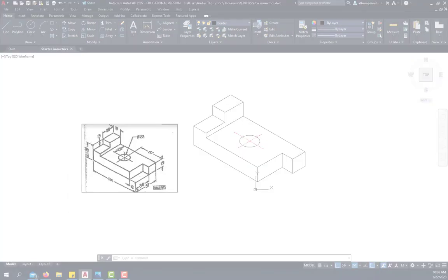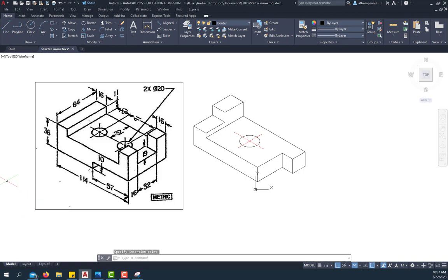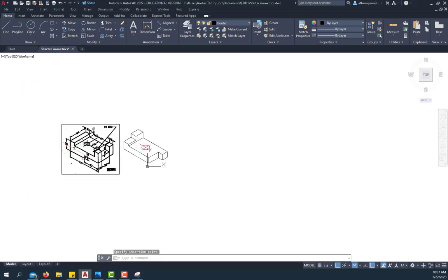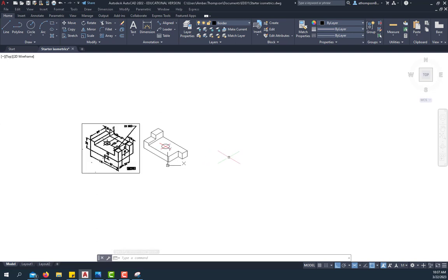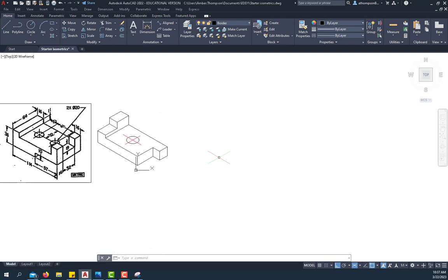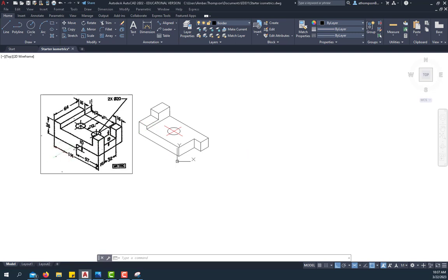And we're going to do another one together, and then I'll let you guys do the last two on your own. So I'm bringing this one in here so we can do it. And we'll just go over a little bit to the side. You know, when we're in AutoCAD, we can move these to wherever we need to move them to. So it's not a huge deal if we start in the wrong spot. But we can see that this one is indeed 114 again in the width. So just make sure your ISO snap is still on and your ortho is still on.